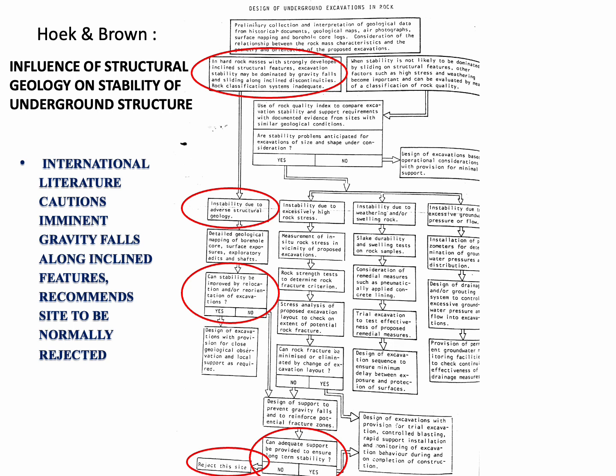Instability due to adverse structural geology affects such structures. Detailed geological mapping of the borehole core, surface exposures, and exploratory adits and shafts needs to be done,